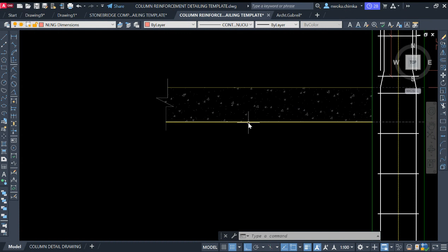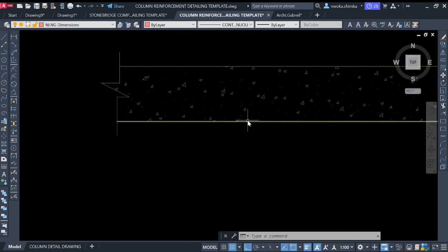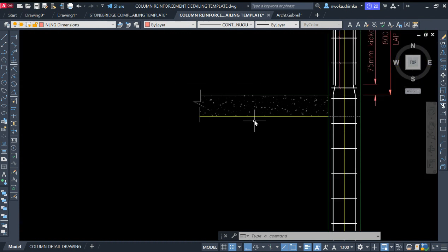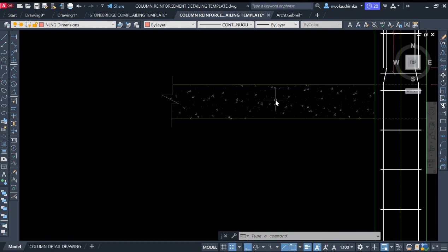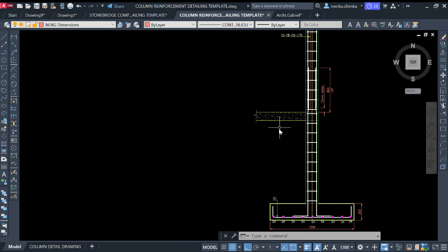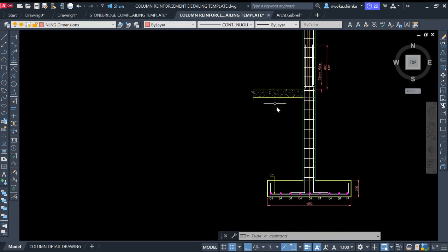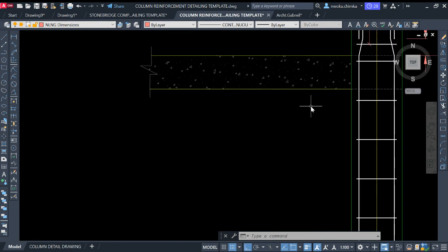So next thing is to offset our layer, damp proof course, and know that there are some layers under this slab because this slab does not directly sit on the soil, because there will be soil at this place. So first of all, we offset our layers first.